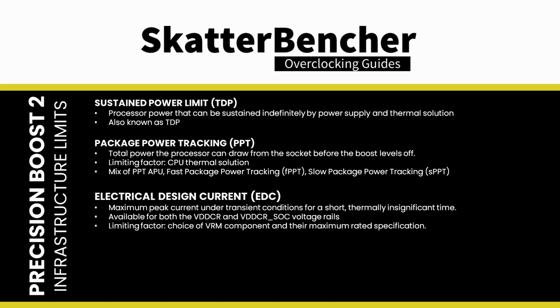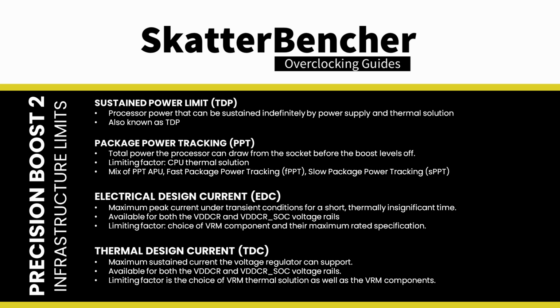Electrical design current, or EDC, represents the maximum peak current the voltage rail can demand under transient conditions for a short, thermally insignificant time. Independent EDC tuning is available for both the VDDCR and VDDCR SoC voltage rails. Typically, the limiting factor is the choice of VRM components and their maximum rated specification. Thermal design current, or TDC, represents the maximum sustained current the voltage regulator can support. Independent TDC tuning is available for both the VDDCR and VDDCR SoC voltage rails. Typically, the limiting factor is the choice of VRM thermal solution and the VRM components.